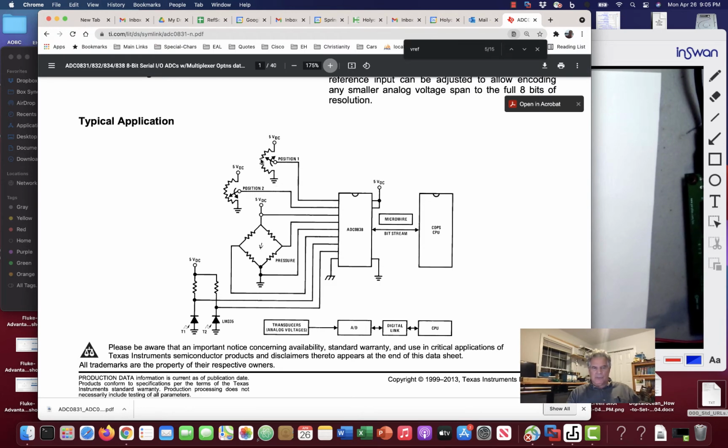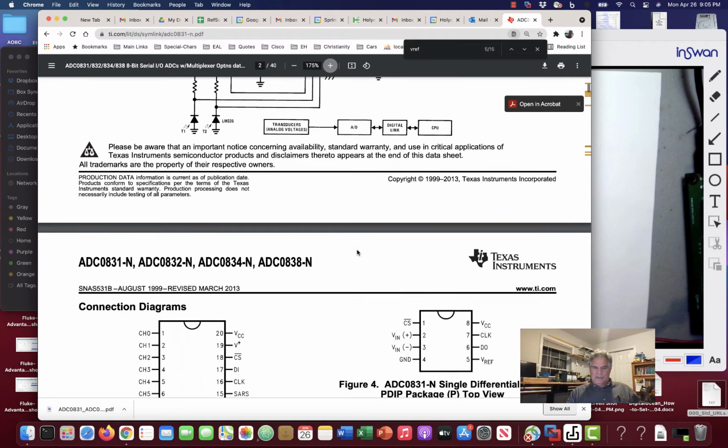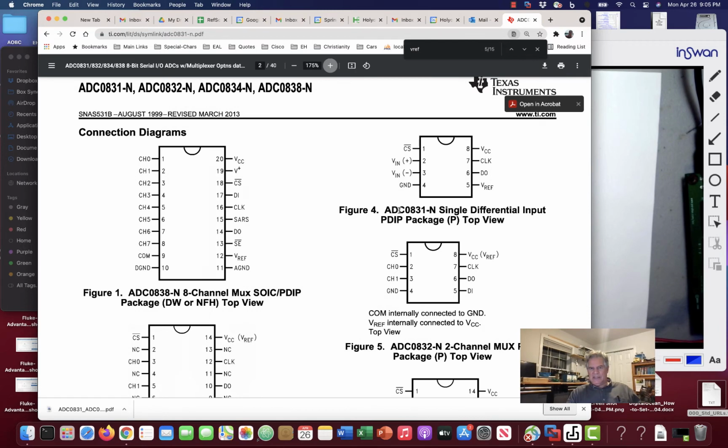See, one side of this potentiometer is at ground, and one side is at 5 volts. And there's the wiper, so out here I build a voltage divider that can go anywhere from 0 up to 5 volts, and then I can put that into an analog to digital converter. In our case, I'm going to put it into an ADC0831, and there's a signal here called chip select, and so it kind of enables the chip. And if you see the bar over it, that's a Boolean algebra notation. It means this signal is active when it is low.